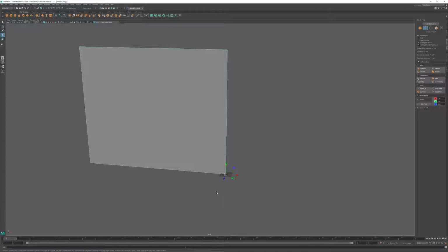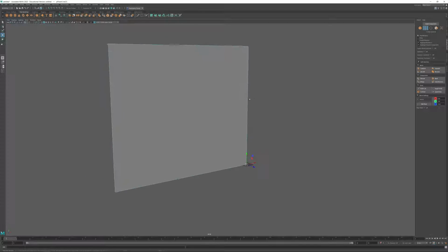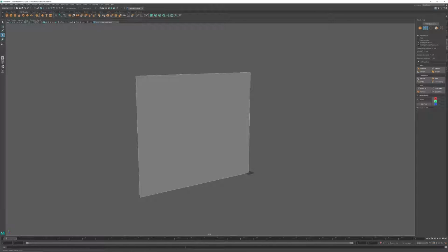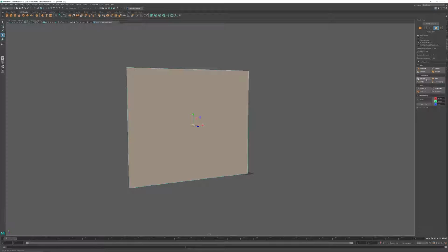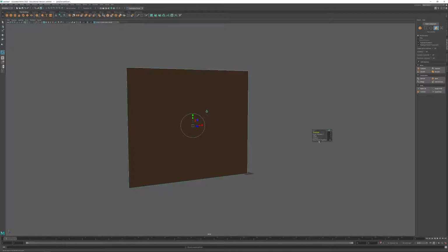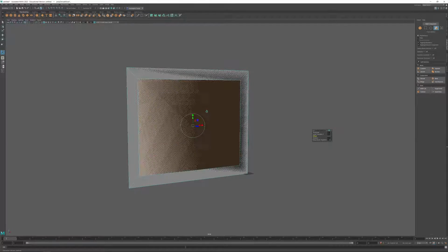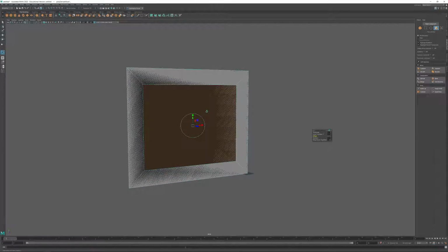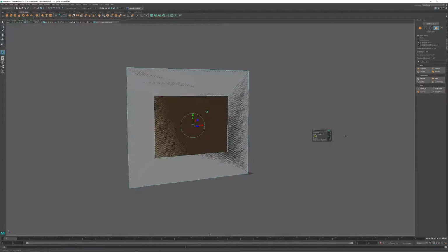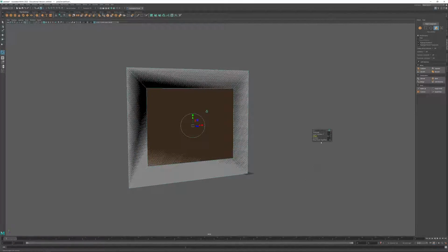The next thing that I want to do is actually go and create some of the details herein. We have just a single facade here, which is not going to work. So I'm going to grab the 2 side edges. Actually, let's do this with the face. I'm going to grab the face. I'm going to use the extrude button. And in the tool that pops open, I'm going to use the offset while holding control. And I will drag this until we get something that's a little bit closer to the shape of the windows that we're after. So they look to be about here.